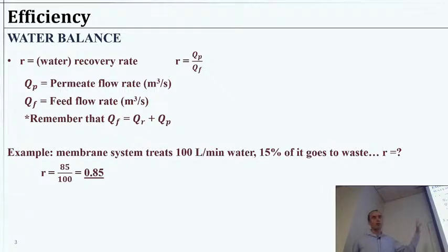But I'm just following the typical conventions here with the R's. Sorry that there's multiple R's. The lowercase r here, we're talking about water recovery. A lot of times we will be interested to know how much water we are processing and recovering from our system, given that we often have to, at least in continuous operation, lose some water for that concentrate stream. Of course, we could flip that if we're concentrating something on purpose, like orange juice or the algae. Maybe that's different.